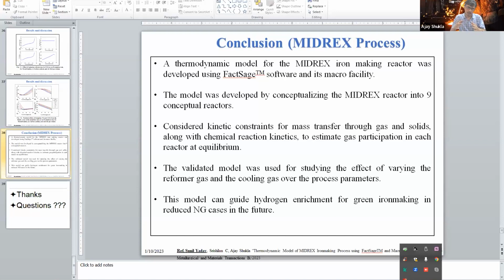But if the reactor is not in equilibrium in totality, what we can do is that the bulk reactor is not in equilibrium, whereas some localized regions are in equilibrium, and we can connect them through the flow of streams. Those flows of streams may be defined by kinetic parameters, maybe by the velocity calculated by some CFD software, or maybe some mass transfer coefficient, or some diffusion coefficient.